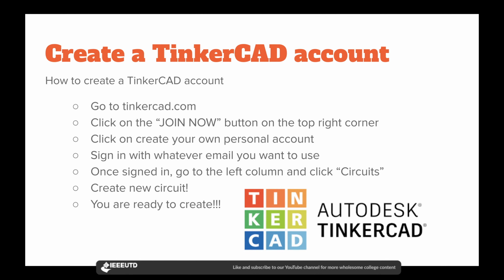I'm going to ask y'all to create a TinkerCAD account if y'all haven't done that. How you do that is you just go to tinkercad.com, click join now in the top right corner, click on your own personal account, and sign in with whatever email you want to use. Once you've signed in, you go to the left column, click circuits, and create a new circuit. I'm going to do the last two with y'all, or the last three. But I'll wait here for a couple minutes for y'all to do that.